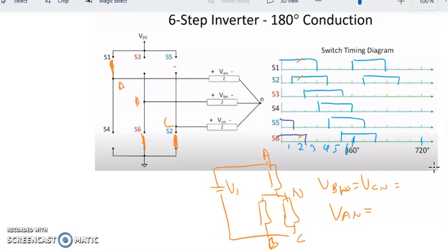So as we know, for single resistor, the voltage drop is 2/3 of V source. Meanwhile, for pairing of resistor here, the drop is 1/3 of V source. So two resistor in pair, the resistance will be lower, so voltage drop is low. Higher resistivity, this is the voltage divider rule, single resistor. So we have here the voltage drop is 2/3 of the source.